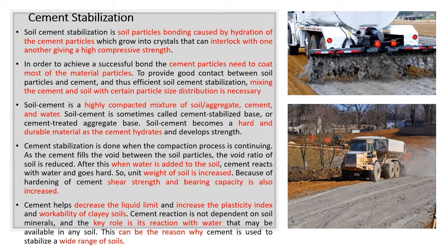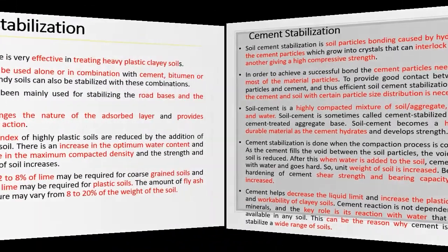Cement helps decrease the liquid limit and increase the plasticity index and workability of clayey soil. Cement reaction is not dependent on soil minerals, and the key role is its reaction with water that may be available in any soil.